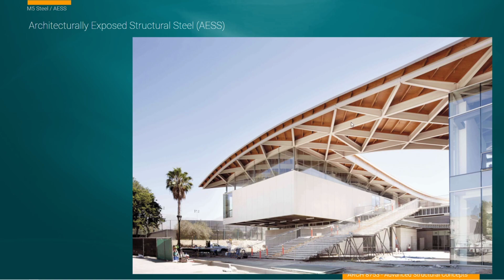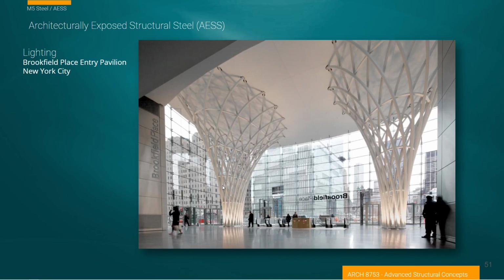We have a wooden deck with its cross members and that wood exposed, but the underlying space frame kind of techniques that we've used in our creation of form being used to generate our patterns for our steel gridded system. The unique features here, you can notice how all of these members in the interior of the frame are about the same depth. But as we get to the edge condition where there's no extra load coming from another member, these are actually tapering down. And then this final exterior element is of less depth than the interior ones are.